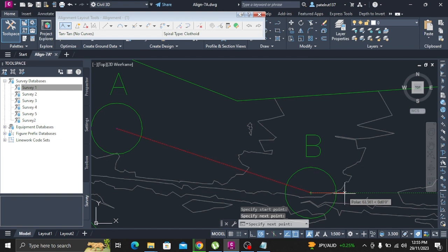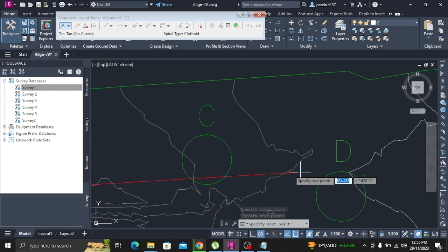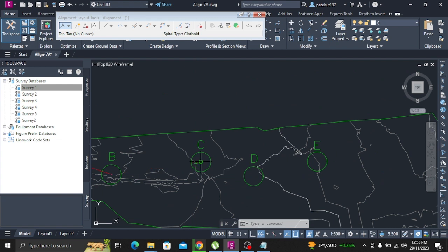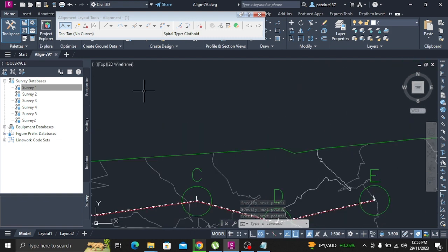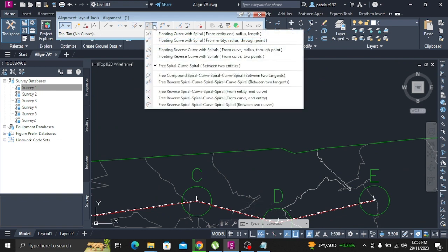Correct design criteria violations. In the Alignment Layout Parameters window, on the Layout Parameters panel, change the spiral in length value to 33.000 m. Press Enter. Change the spiral out length value to 33.000 m. Press Enter. Change the curve radius value to 100.000 m. Press Enter.